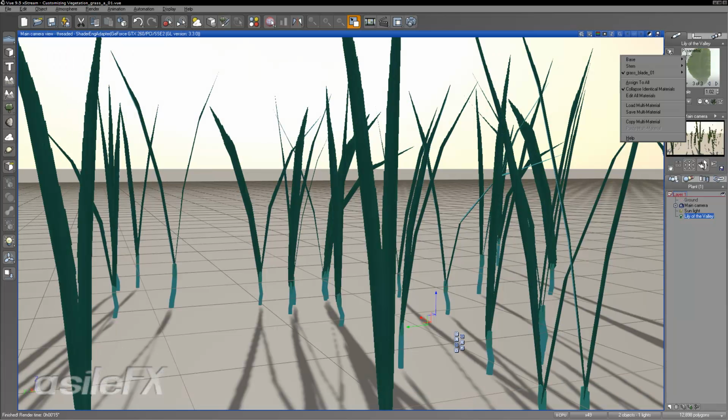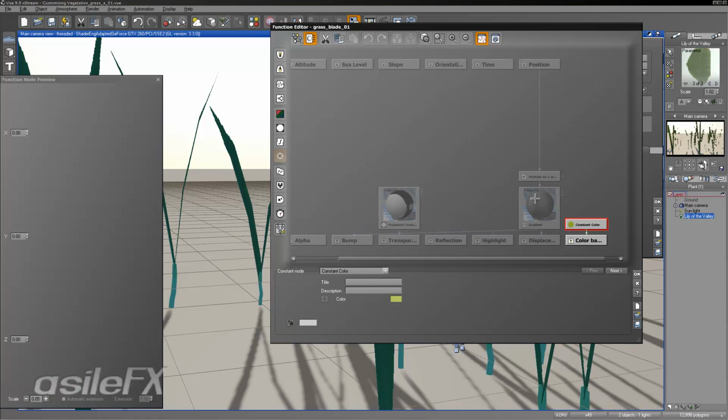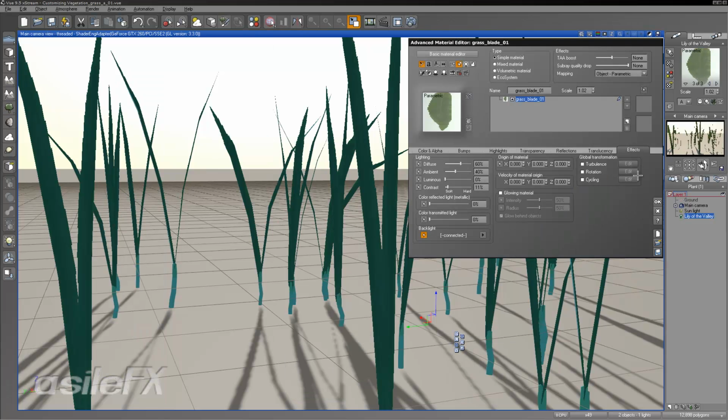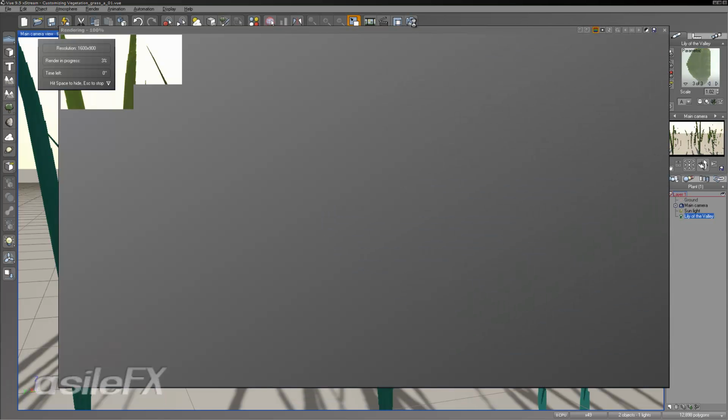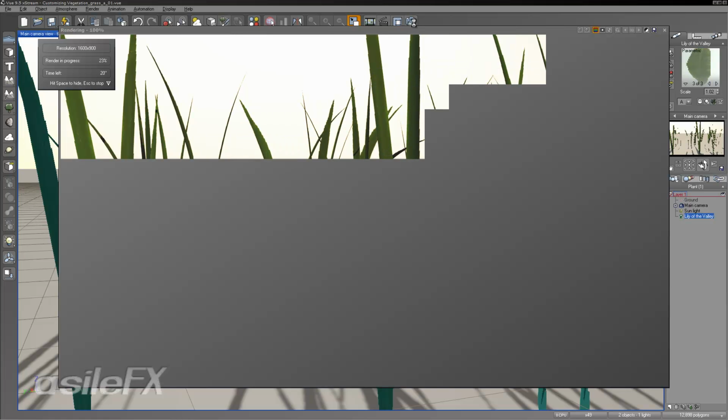And if the backlight color isn't bright enough, what you can do is either adjust the levels within the image and grab a new color, or it really doesn't have to be perfect. So we can just go back in, and what you can do is go to the color and increase the lume value. And that should give us a higher output, closer to that other color.